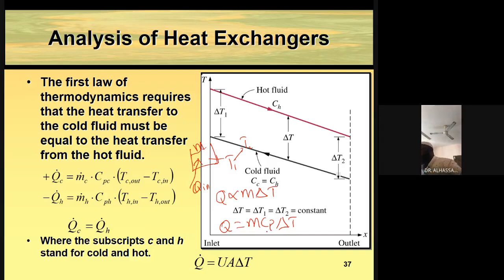And Cp is the specific heat capacity at constant pressure. Be careful, the unit for this is in kilojoules. If you want to express this in terms of mass flow, assuming the fluid is flowing, for example in a heat exchanger, then we divide this by time. Then eventually we have Q dot, the rate of heat transfer, equals M dot Cp times delta T. And this unit is in kilowatts. So this equation is similar to this.